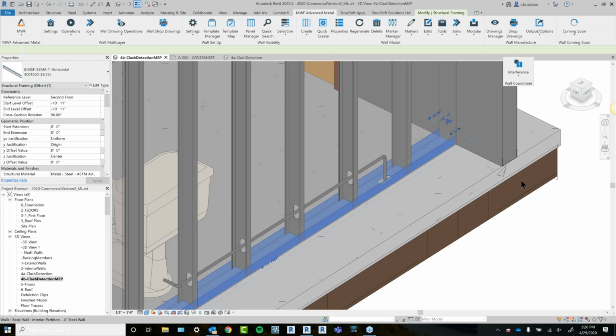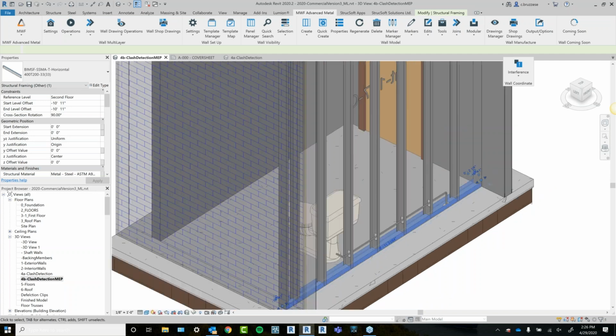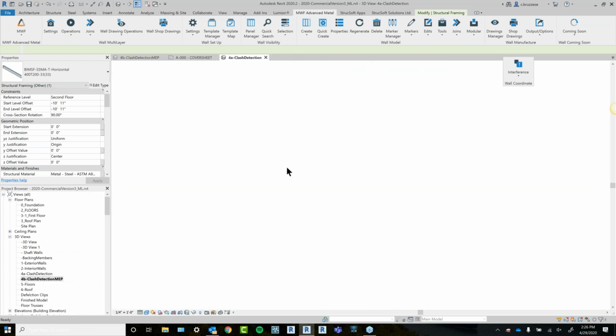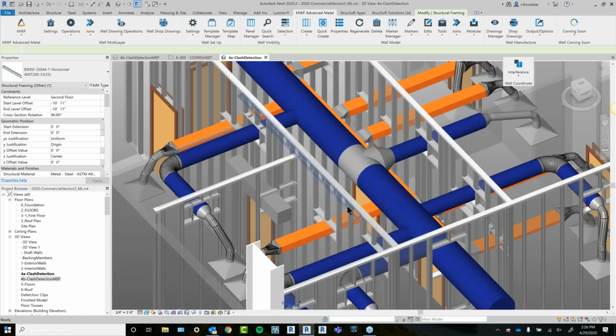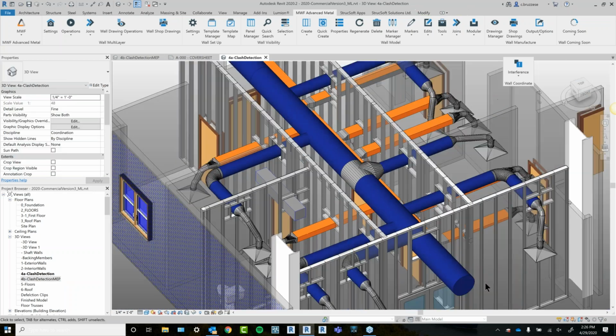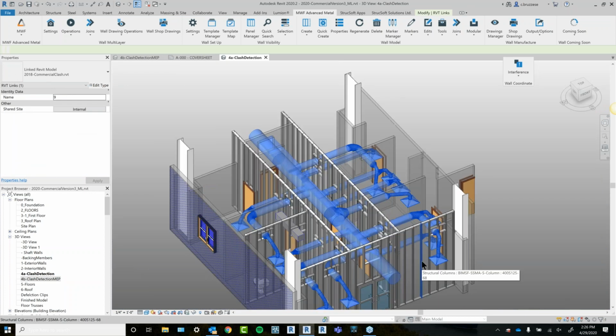All right, Christina, looks like we have a question that came through our dashboard. What are the other types of models aside from Revit that we can use to clash? NWD, IFC, 3D AutoCAD? Yeah, so CAD files will work fine, as long as they're 3D.